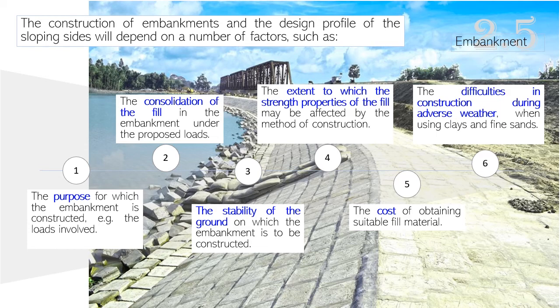The extent to which the strength properties of the fill may be affected by the method of construction. The cost of obtaining the suitable fill material and the difficulties in construction during adverse weather when using clays and fine sand especially.